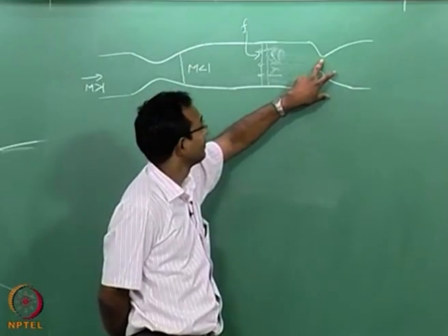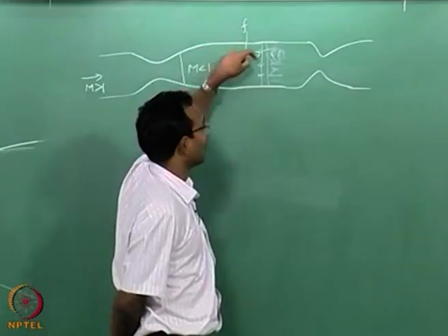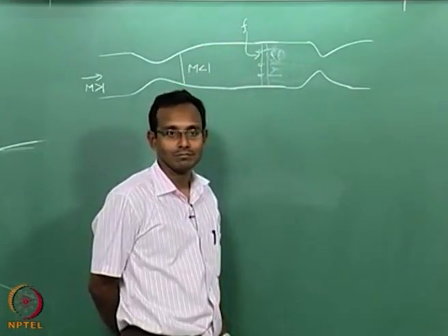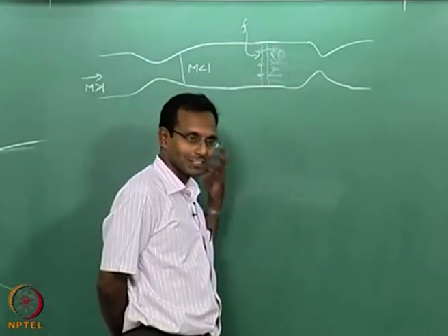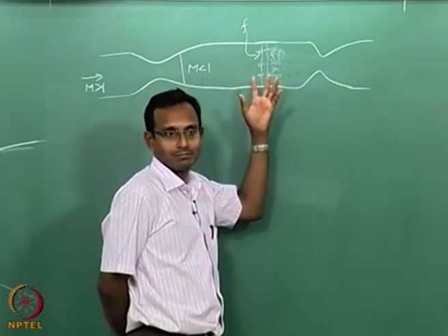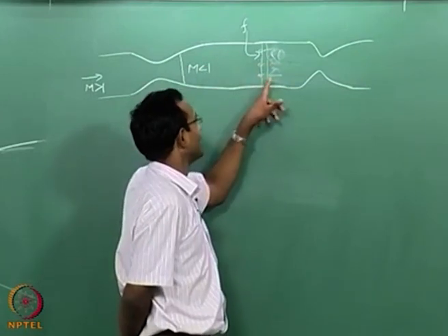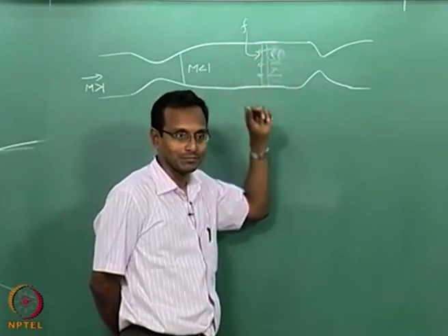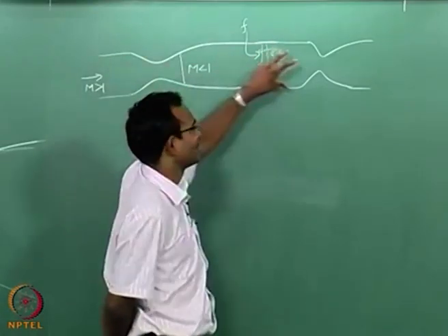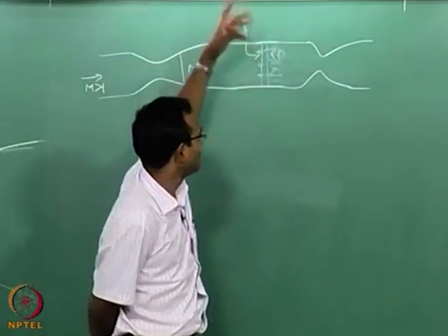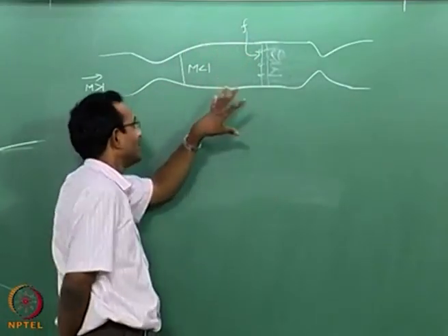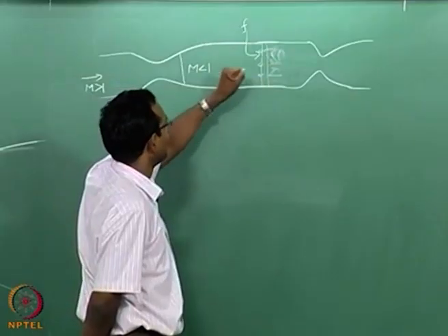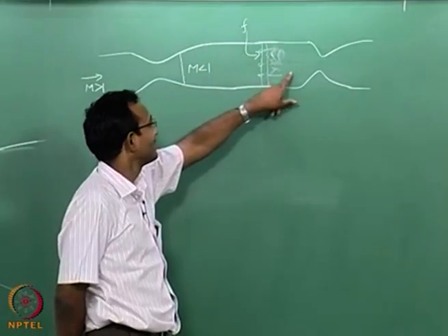If it is choked here and I add a little more fuel to this, what happens? First thing, mass choking. Or if I do not think about mass choking, there could be combustion, more heat release, thermal choking. Oh, in all this I did not talk about friction choking, that is also there. Every choking possibility is always happening there. After all this, if there is choking, what happens in this region?